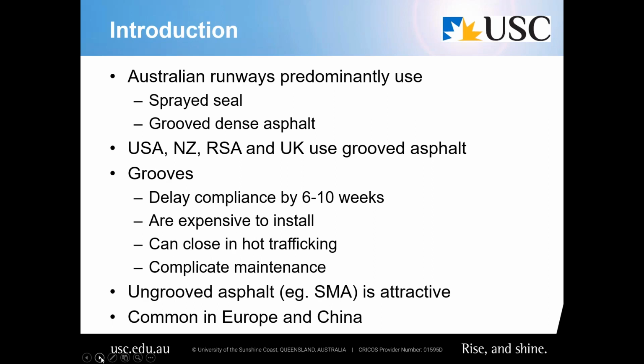Most of us would be familiar with grooves. We usually install them 6 to 10 weeks after the surface is built. In that period in between, our compliance is questionable or marginal, because we need the grooves before we'll comply. We know they're expensive. A significant airport could spend $500,000 putting grooves on their runway after they've resurfaced it. They can close in under traffic in hot conditions, and they can complicate maintenance in terms of rejuvenation or preservation treatments. They don't make those things impossible, but they certainly make them a little bit more complicated than they would be.